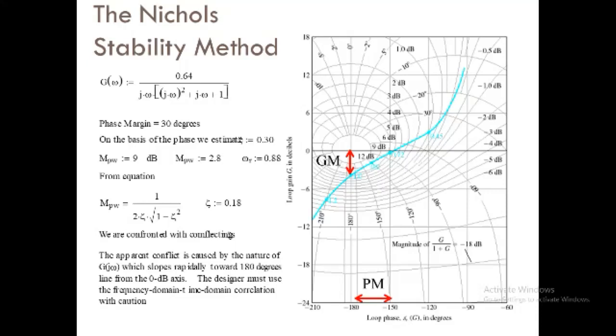This is the x-axis, and on the y-axis is a normal scale, that is an equally spaced scale. Each bold line on the y-axis is 1 inch and is subdivided into 0.1 inch, with each 0.5 inch slightly darker. We plot the magnitude and phase on this scale. Since both graphs must be drawn on the same paper, the scale must be chosen properly. Suppose we choose the leftmost one as 0.1 rad per second.